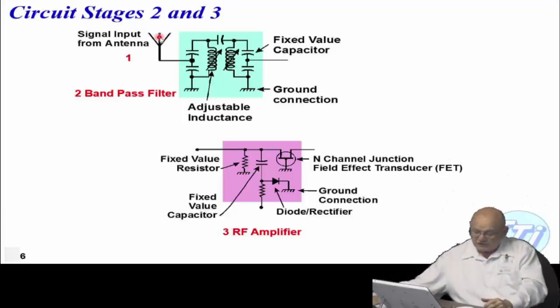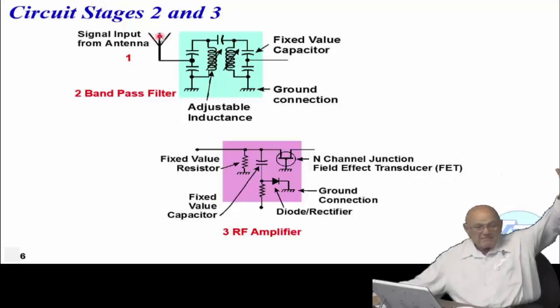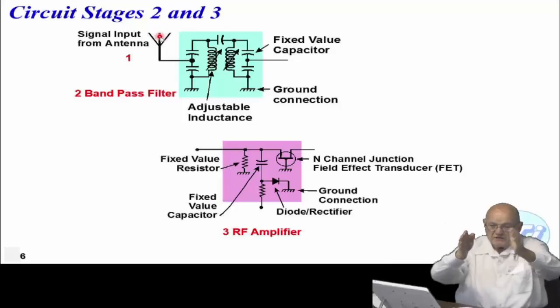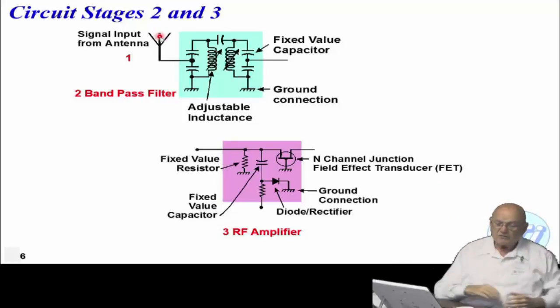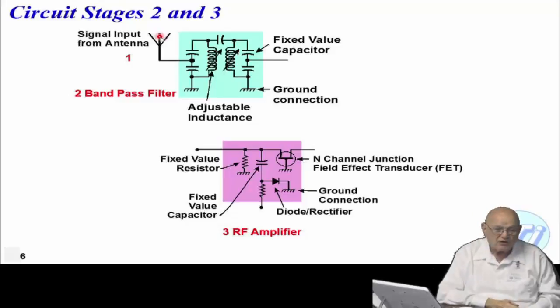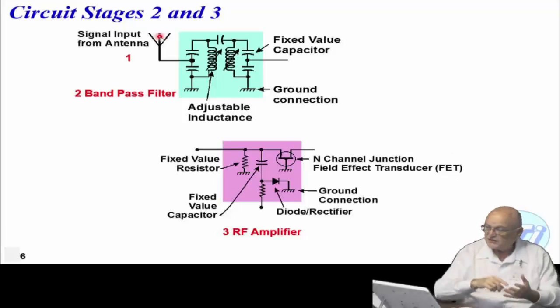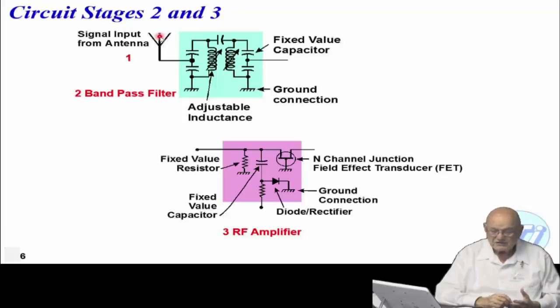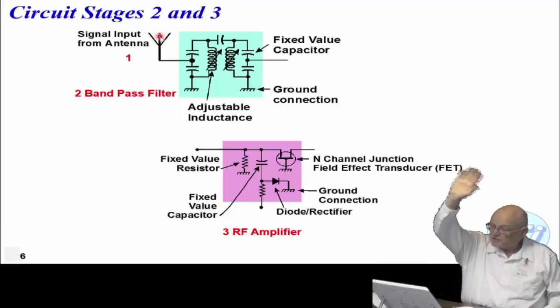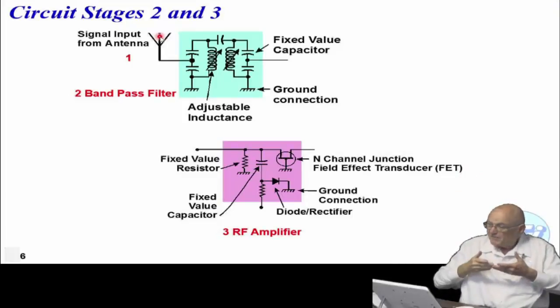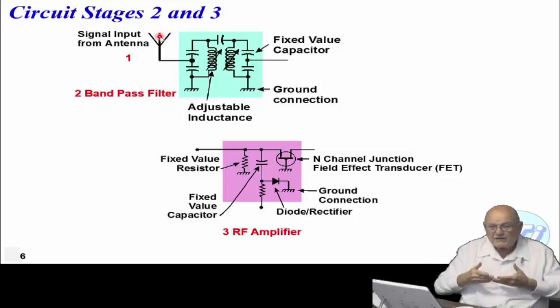But what I wanted to point out to you, here's your antenna, right? It's interfacing with the air, whether you have it up on your roof. You've seen the old TV antennas, haven't you? Where they have the bar and the elements come out longer and longer and longer. Well, it turns out air has an impedance of 377 ohms. By the way, impedance is the term used to describe the resistance, inductance, and capacitance. It's a general term, and we'll learn more about that at the end of today. So if the air has 377 ohms, what should the antenna's impedance be to get maximum power transfer? That's correct.